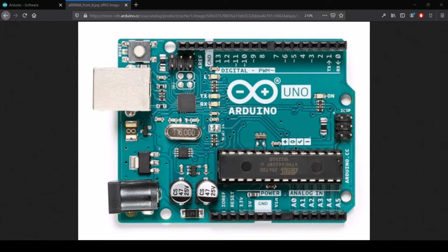But there is another LED which we can actually use and program for whatever we want. And that's this one right here. This is a general purpose, just a normal LED, which we can program. This LED is actually connected to pin 13. It's kind of hard to tell by lining it up, but we just know by default. Also, if you look at the schematic, pin 13 is what controls this LED.